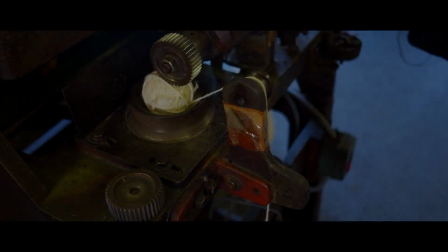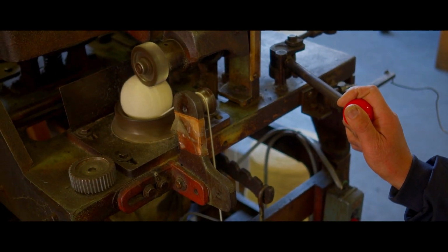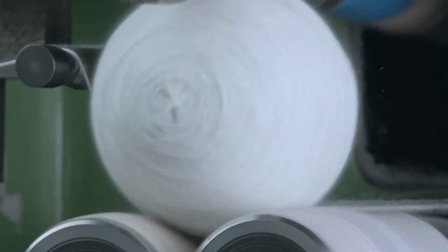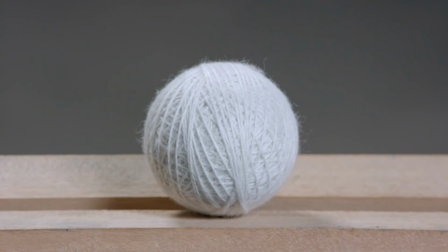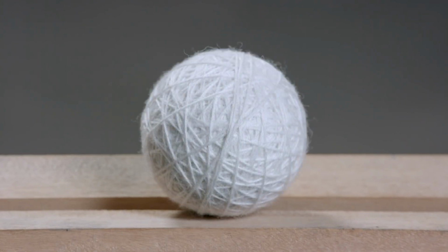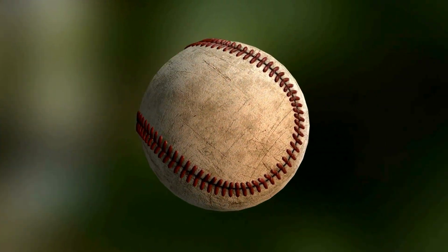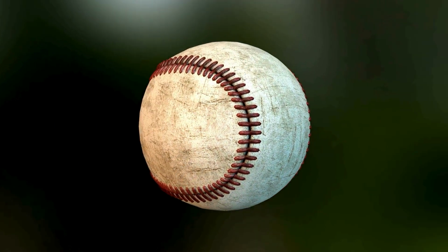Windings. Surrounding the pill are four distinct layers of yarn windings, which help maintain the ball's shape and add to its resilience. The first wool layer is the thickest, bringing the unfinished ball's circumference to 7 3/4 inches, 19.68 centimeters. Each subsequent layer increases the ball's circumference until it reaches the standard size of approximately 9 inches, 22.86 centimeters. Wool is chosen for its natural resilience and ability to return to its original shape after being compressed, ensuring the baseball retains its perfect roundness despite repeated impacts.